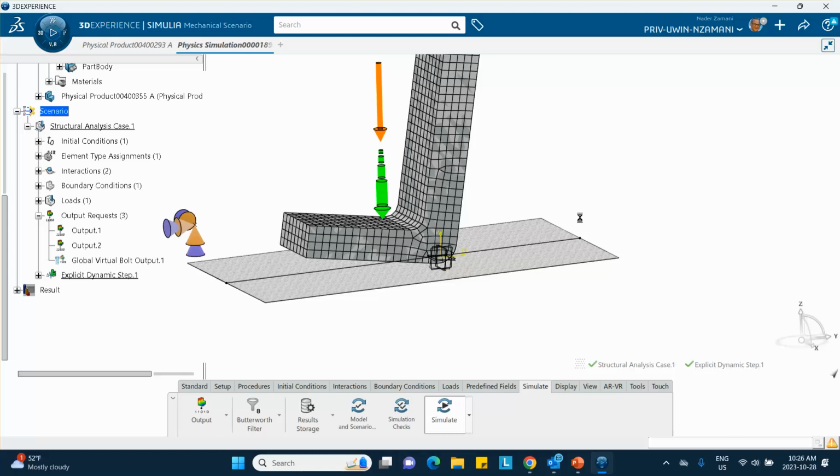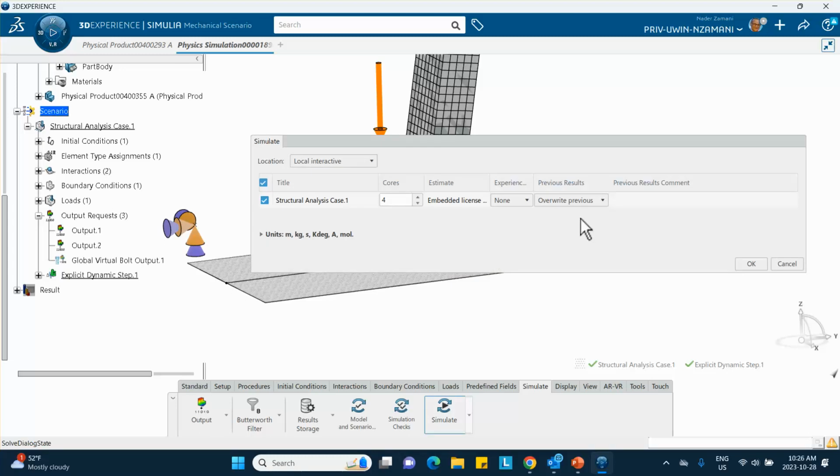I can tell you that based on what the reference is indicating, this mesh is too coarse, and he makes a finer mesh. And why he did that is he plots the data for artificial energy as a function of time, for example, and total energy versus time, and a substantial portion of that artificial energy is a substantial value. Okay, so all right, now it's the run.